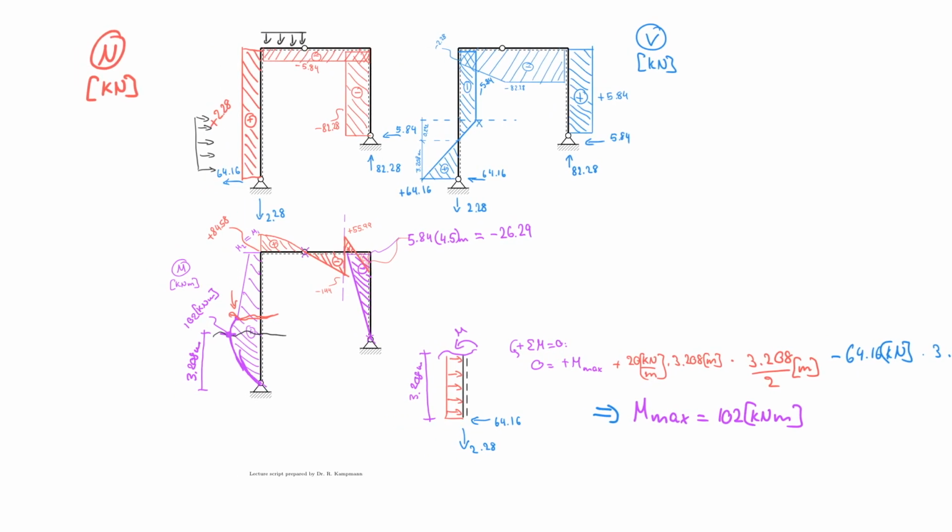So now we have drawn for the first time the internal force diagrams for a rectangular frame: normal force, shear force, and moment. As we did before, we used the same logic. For example, for the normal force, tension and compression is important, and it defines our positive and negative values. If nothing changes, then it's just constant, and that's mostly the case for us in this class. And we were able to follow that logic here.